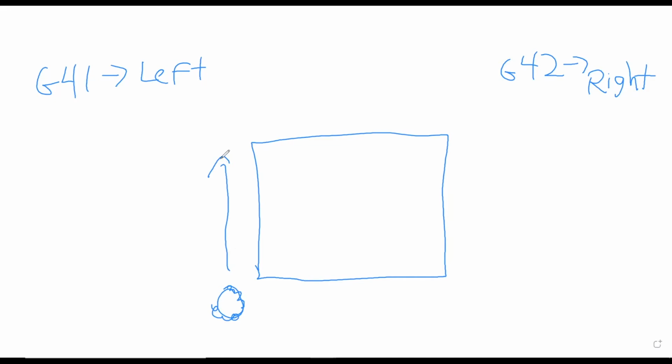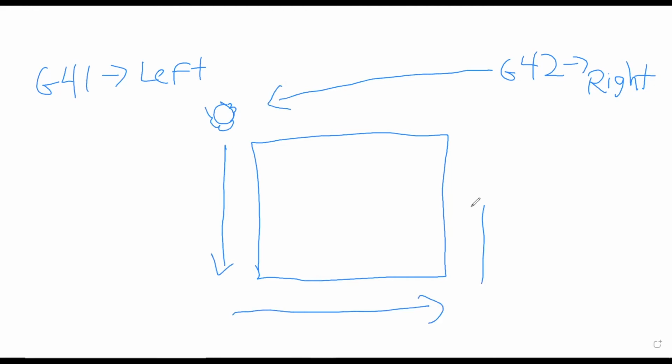Now, if we were to use G42 and we're heading this direction, then our tool would be on this side over here, and we'd end up cutting the workpiece too small. Well, we could use G42, but we would have to conventionally cut, and we'd have to come from this way. So that would be G42, and then continue around as we conventionally cut.